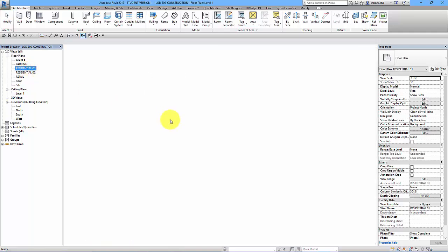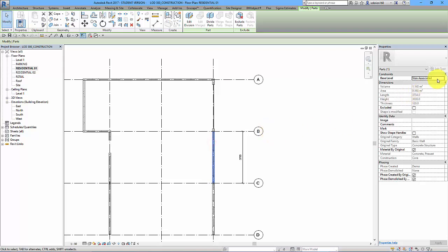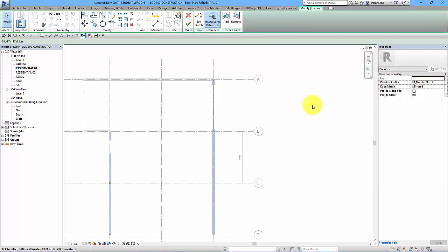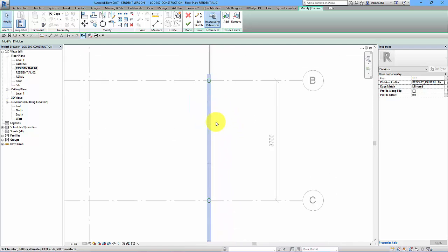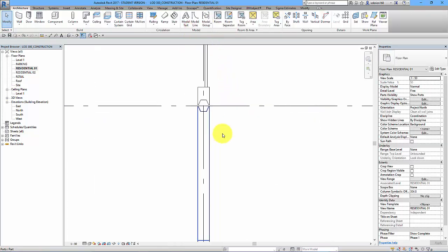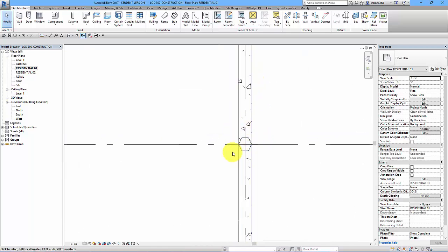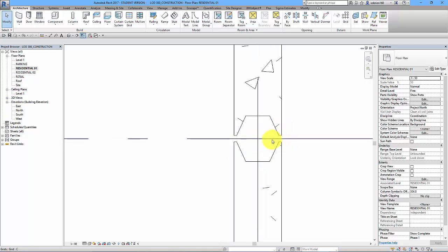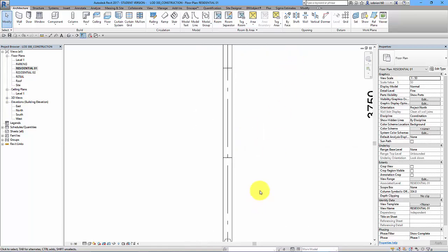go back to the residential level there, and I'm going to select one of them and edit the division. Try this, apply. And you can see we've got some kind of acceptable sketch in there. So then we can accept that. And now I'm using kind of narrow walls here, so it's possible you have a different kind of junction in there. But you can see how easy it is to both deal with the tolerance and also the area for the reinforcement, which you can put in at a later date.